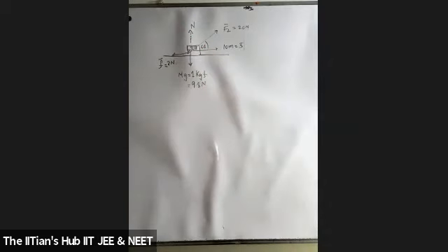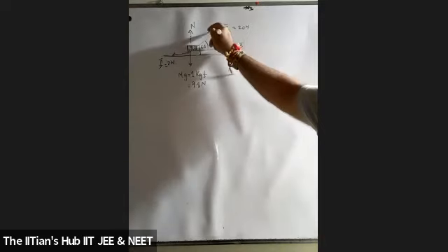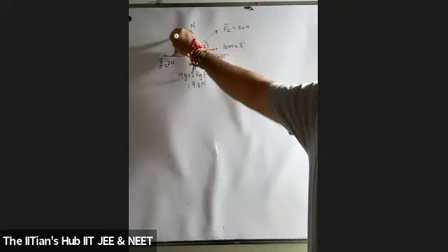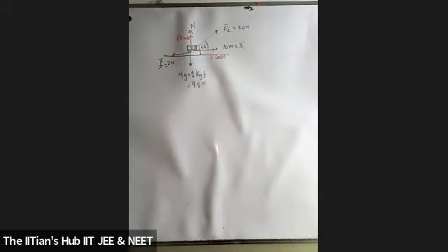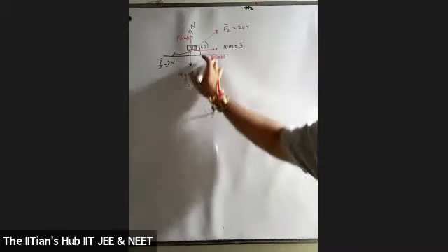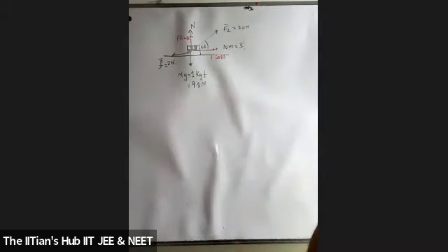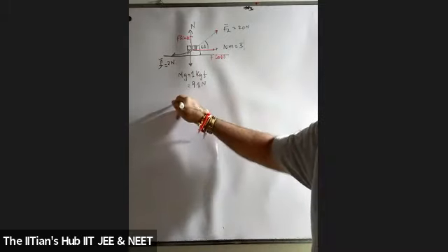If I want to go with respect to an inclined plane, तो मैं क्या करूँगा? Can I say I have to resolve these forces? Sir, ये F अगर act हो रहा है, तो can I resolve this into two components? Yes, sir. तो ये क्या हो जाएगा? F cos theta and F sin theta. Agreed. Yes, sir. Now suppose if I say the body is moving horizontally, students, so should I go for the horizontal forces? Yes. Which are the horizontal forces I consider? F cos theta, for the body to move.